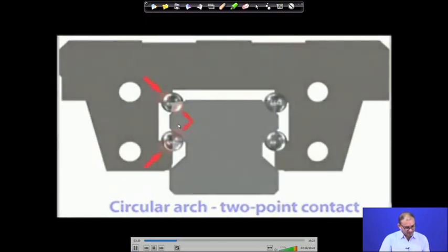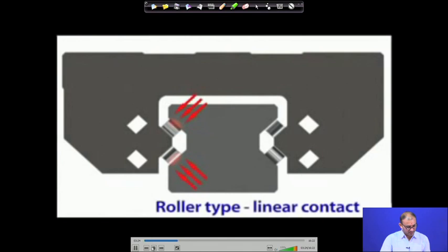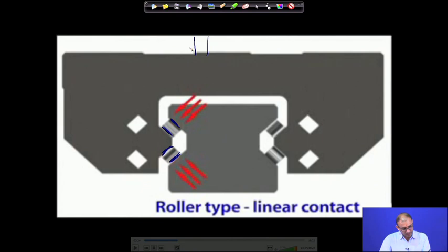Correct. Its centers are contacting inside this part, and now if you use a roller bearing, it is the same thing here, but now you have more contact zone points. It is a line contact now, and because of the line contact your load carrying capacity increases. Now you can apply a little higher load for machining, or doing a little aggressive machining at the micro machining center.